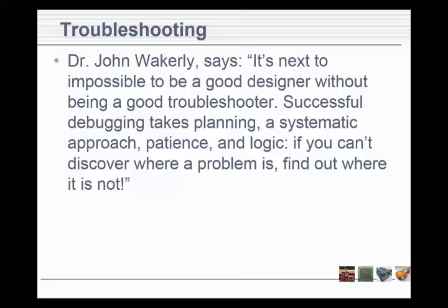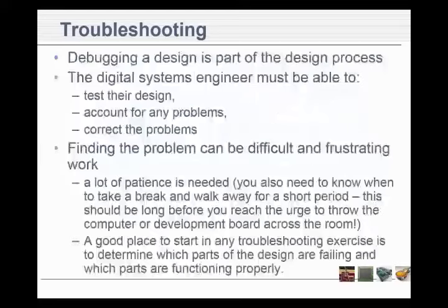And if they were all right, well then I just cut out the first half of that schematic, right? The problem was somewhere after that. If there were problems there, then the problem is probably somewhere up here. And I would cut it in half again and keep doing that until I finally could get in there and find out where the problems were. This is a lot of patience. It is hard to do the troubleshooting.